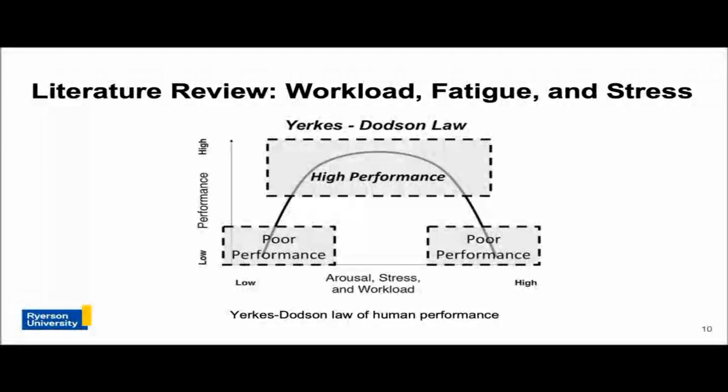The importance of stress management in the flight deck can be best described using the Yerkes-Dodson law of human performance. As seen in the figure, human performance is highest at some intermediate value of stress, workload, or arousal. When workload is low, human performance decreases due to inattention and boredom.